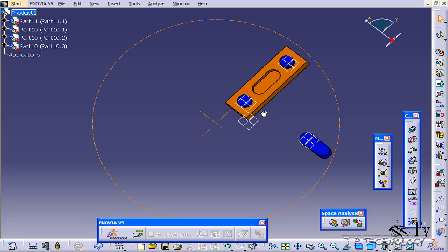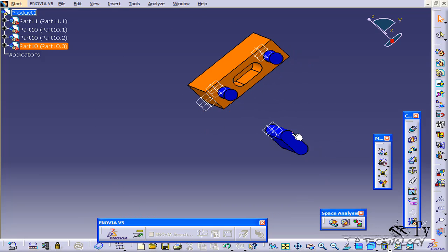Now with a part such as this is where we're going to run into problems with using the snap feature. When we used the coincident mate before, we're able to make a coincident mate between this axis here and this axis here. When we make the other coincident mate, you have like a pivoting point, and this will whip around and you'll have it slotted in. Now I'm going to try to do the same thing using the snap feature, but you're going to see that we don't get the result we want.